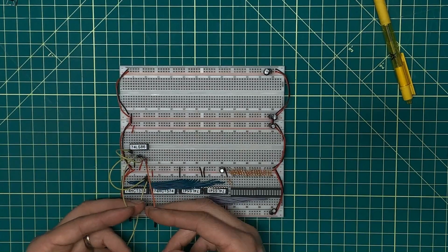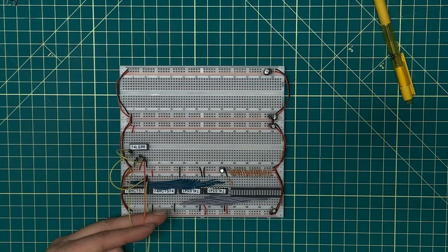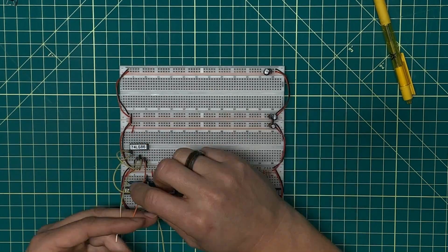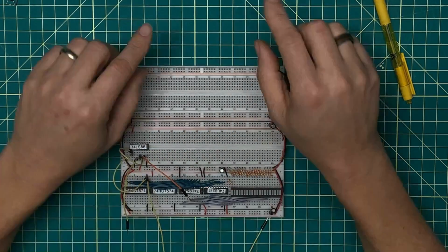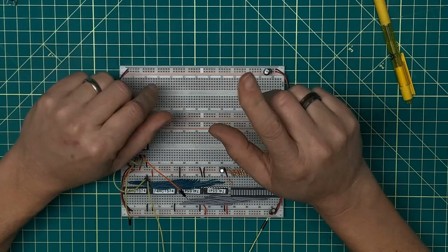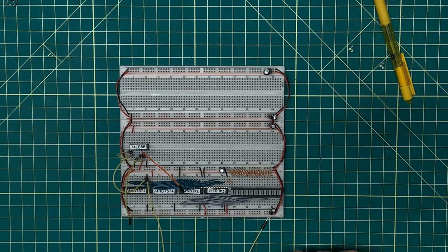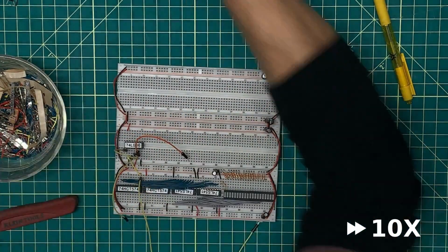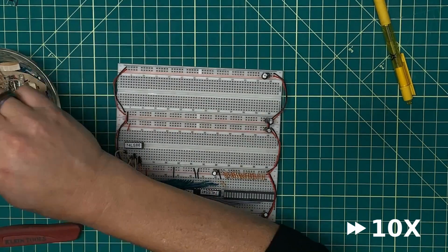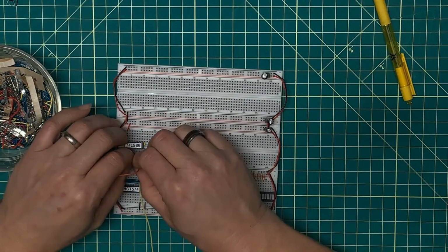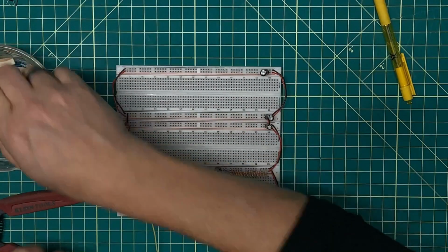Now, clock and inverted clock, since both signals come from the clock module, they're all tied together in the same node here. They should be exactly the same timing coming out of this exclusive OR, which means that when I look at it on the scope, I should have a uniform rise and drop at exactly the same time. Let me get this wired up real quick. Okay, so here are my two clock signals that are going to go out to the rest of the module here.